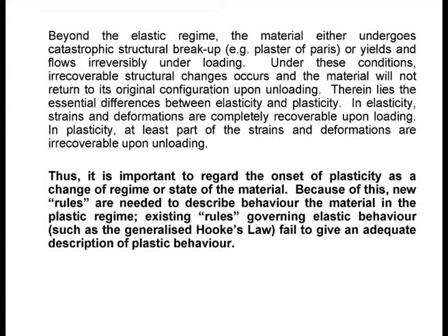So whether you like it or not, if your stress level is high enough, there will be some change of regime coming up. A change of regime could be a catastrophic failure, it could be some kind of non-linear behavior, or it could be the onset of plasticity.